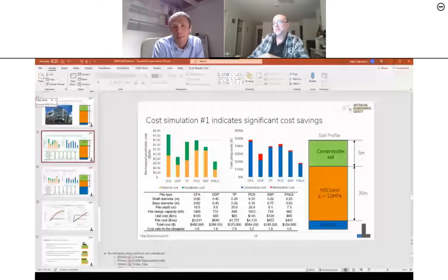It's actually a bit opposite to what some engineers think, that enlarging the diameter of a pile increases its strength in bending. Well, it does if the bending comes from external loads, but if it comes from lateral soil movements that the pile cannot prevent from happening, it basically has to follow the movements. Then the lesser the bending resistance of a pile, the more curvature it can accommodate due to those lateral soil movements. So obviously, yeah, I'm not sure if I answered the question.